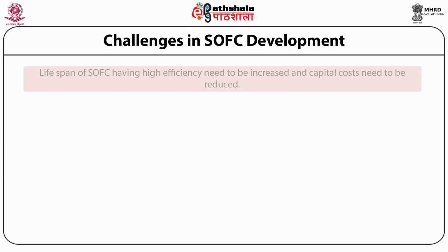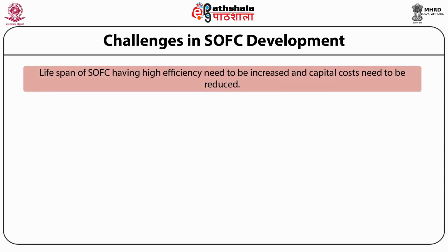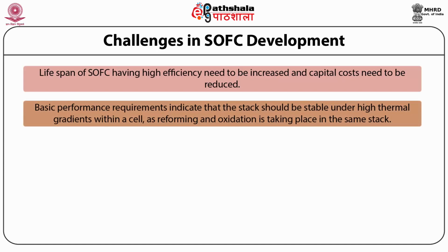The lifespan of SOFC having high efficiency needs to be increased and capital cost needs to be reduced. These can be improved only if pre-reforming is not necessary and the electrodes give considerably less overpotential. Basic performance requirements indicate that the stack should be able to withstand high thermal gradients within a cell, as reforming and oxidation are taking place in the same stack.